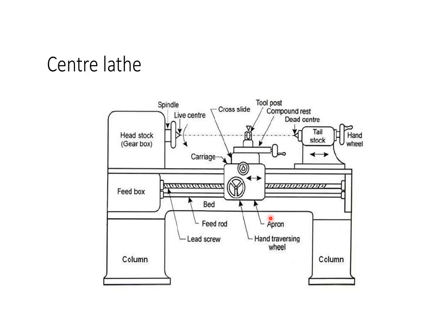First, saddle. First, we know what is meant by saddle. So, saddle, it carries the cross slide. It carries the cross slide, compound rest. See, this is the compound rest and tool post. It is an H-shaped casting fitted over the bed. It moves along two guideways. Cross slide, it carries the compound rest and a tool post. It is mounted on the top of the saddle. It can be moved by hand or may be given power feed through apron mechanism.